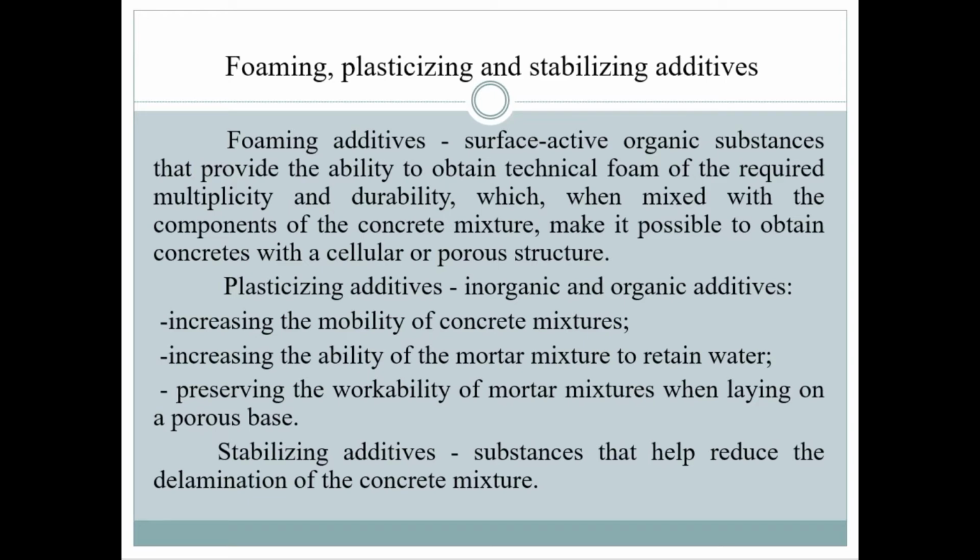Plasticizing additives are inorganic and organic additives that increase the mobility of concrete mixtures and the ability of the mortar mixture to retain water, preserving the workability of mortar mixtures when laid on a porous base. Stabilizing additives are substances that help reduce the delamination of the concrete mixture.